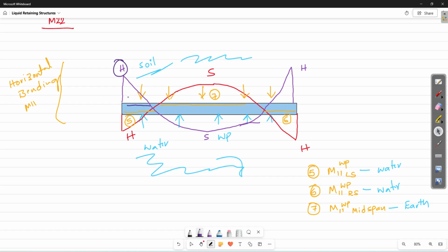So it is reinforcement number 8. For this sagging, you will provide steel here. Okay. For this hogging, you will provide reinforcement here. Okay. So 8, I will call this as 9, and I will call this as 10. Okay. So 7 completed.